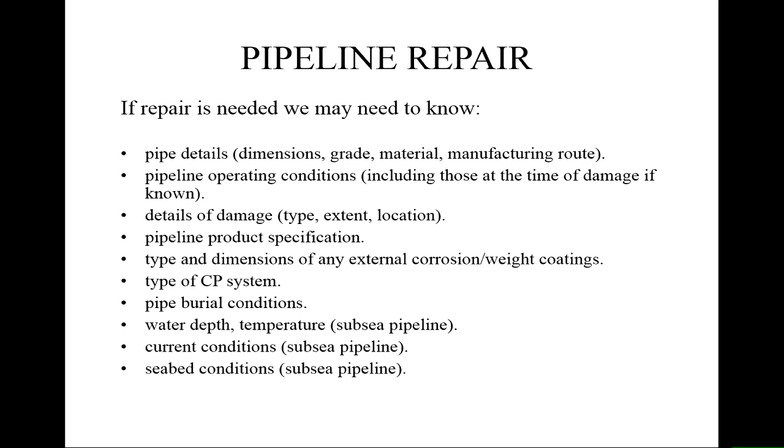What type of damage is that? How extensive, and where does it occur on the pipe? The product specification. What is the use of the pipe, to carry what? Is there any corrosion, any anti-corrosion protection? Cathodic protection, is there a cathodic protection present?